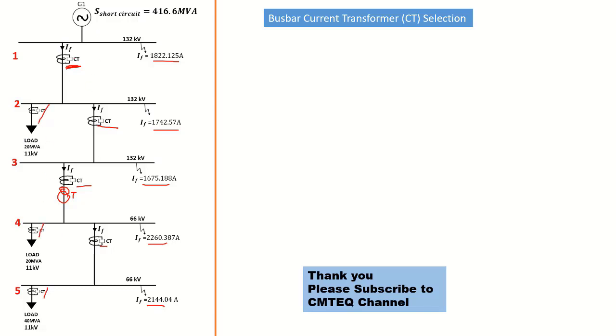So this current transformer must be able to know what the normal current flowing here is, and in a situation where that current is no longer the same, now it's a short circuit current, the current transformer needs to tell the circuit breaker, listen, the current value is no longer what it's supposed to be, so you need to break. And the circuit breaker is going to break, open up, and protect the equipment or the personnel. So that's what we're going to do in the next tutorial.